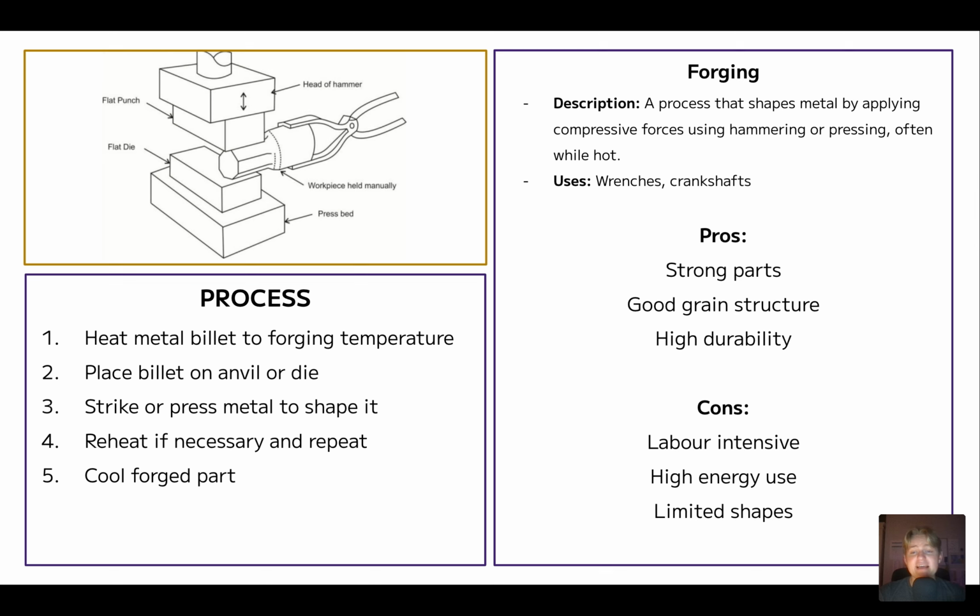The cons of it is that it is very labor intensive, especially if it's being hammered instead of using some sort of a process. But even still, it's labor intensive, and you need an experienced operator, which increases the cost. And if you are using a hydraulic press or an automated press, something where you're not hammering it, then that is going to seriously contribute to some energy costs, and that's got environmental and, as I mentioned, cost considerations. And we're limited to the shapes that we can create with this process, really.